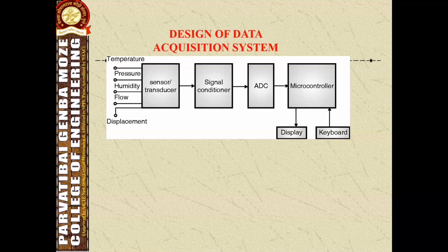The signal conditioner block is used to produce the conditions so that the circuits work properly. Signal conditioning may include amplifying the weak signal to the required level, modifying the data, providing excitation, balancing the circuits, and filtering out unwanted noise. For designing a signal conditioning circuit, the person must be well versed in op-amp design, and it is a critical stage to design because the input signal is weak and has a lot of noise in it.